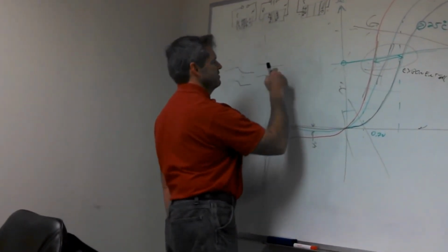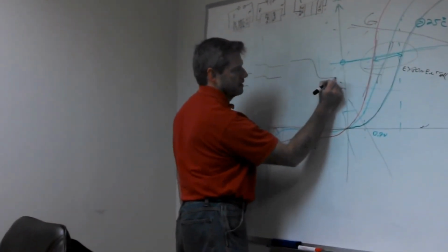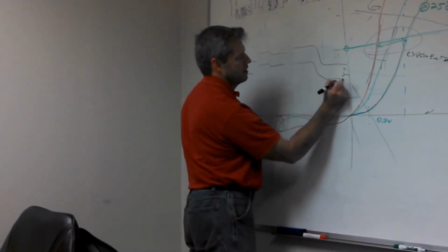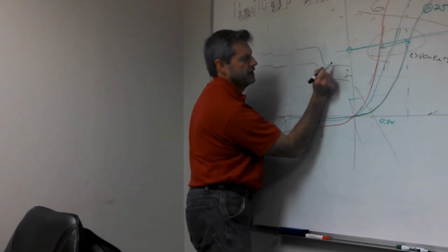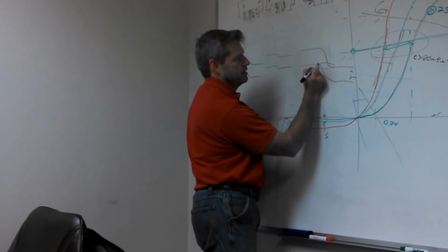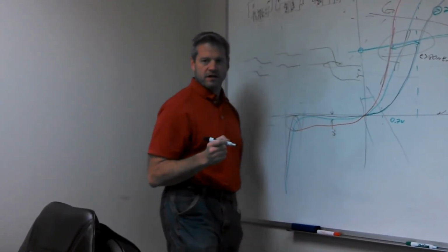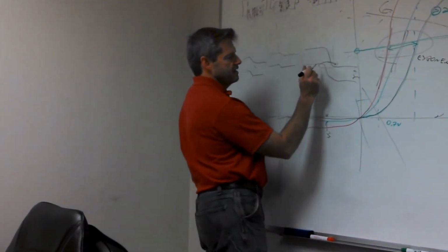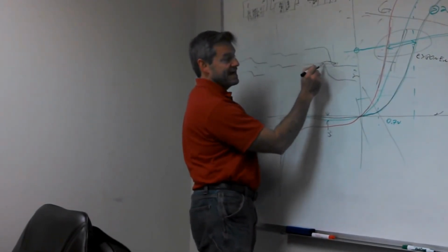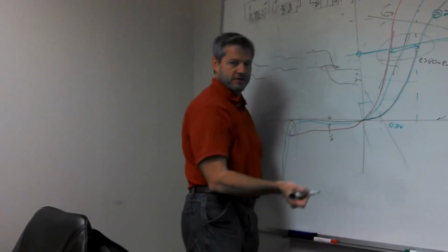And what happens is, in the band diagrams, this gets steeper and steeper. But what you've got here now is a place where an electron can tunnel over. So we get quantum tunneling effects. And this electron can just hop right over to that side, because that's actually easier than jumping up into this band or any of the other things.